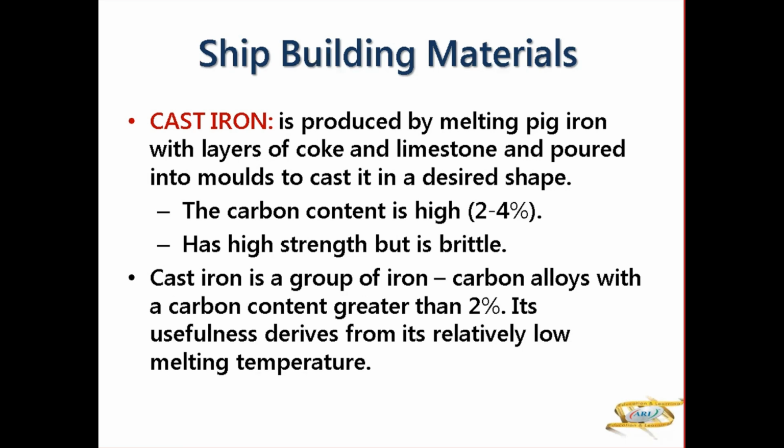So cast iron welding requires special welding rods and all. You can't do cast iron welding with normal welding rods. So special rods are used for this, and strength is high, but cast iron, if it falls, it can break, so it is brittle. So it is a group of iron carbon alloys with carbon content greater than 2%.